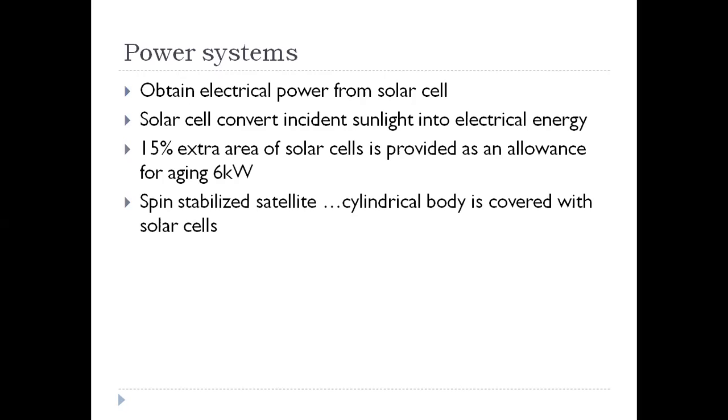In the spinner design, the cells cool down when in shadow and run at 20 to 30 Celsius with somewhat higher efficiency. The bombardment of the cells by protons and electrons is also more severe, and a thicker layer of glass may be needed to slow down the deterioration of the cell, with a consequent weight penalty.